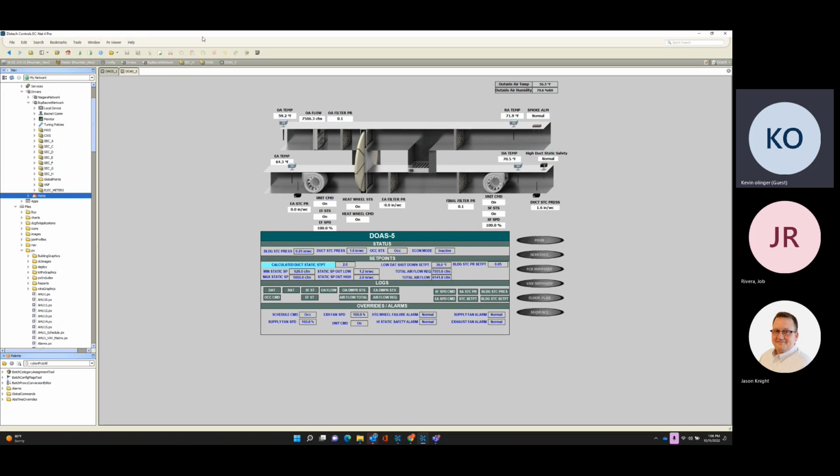So let's revisit smoke in the air, things like that. These are 100% outside air. That's what they do. That's all they do. There's no mixed air dampers. And even though there's filters on them, if we have smoke in the area, the only thing we can really do to keep that smoke from coming into the building is to shut down all the DOAS. Correct.